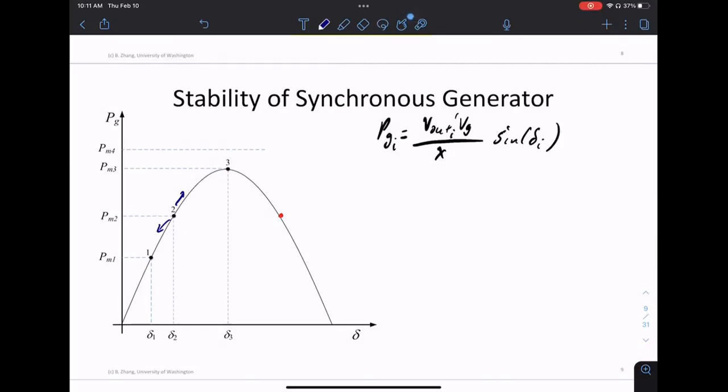So you have a different sign on the feedback controller. This will confuse your controller if you can operate at both ends, because your controller sees this and says, hey, which way should I go? To increase or decrease my angle of operation, I need to know, am I on the left or on the right? Because this requires different ways of changing my active control.